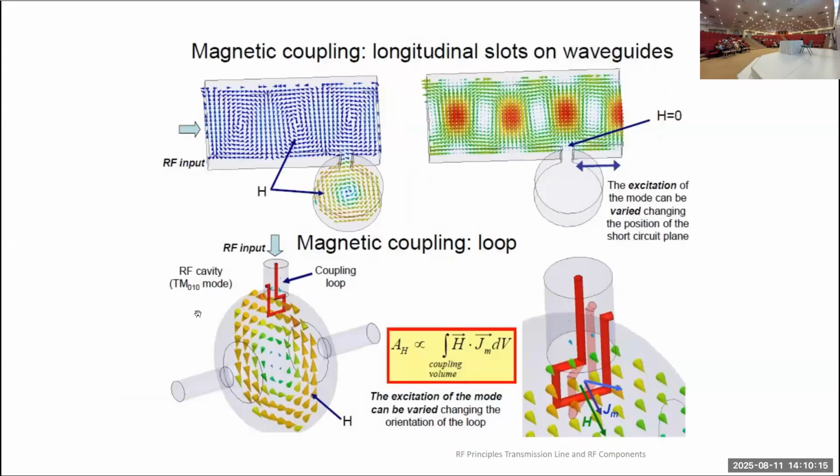Here, again, it is shown where you couple your cavity to get maximum coupling. For example, if we couple our cavity here where the electric field is maximum, no RF power will be coupled because the outer wall of the cavity has maximum magnetic field. But if you couple here where there is a magnetic field maximum in the waveguide, the cavity will be coupled to the waveguide.